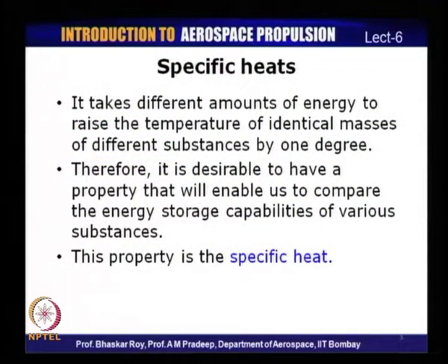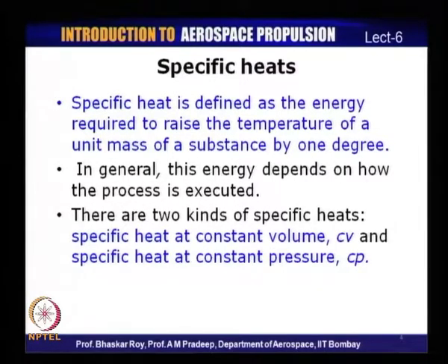Specific heat is a property that helps us understand how much energy is required to raise the temperature of identical masses. So, it is desirable that we have a property that will enable us to compare the energy storage capabilities of different substances. And this property is what we shall define as specific heat. Specific heat by definition is the energy required to raise the temperature of a unit mass of a substance by 1 degree. And in general, this energy depends upon how this process is executed.